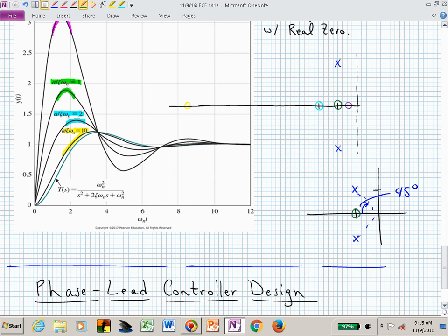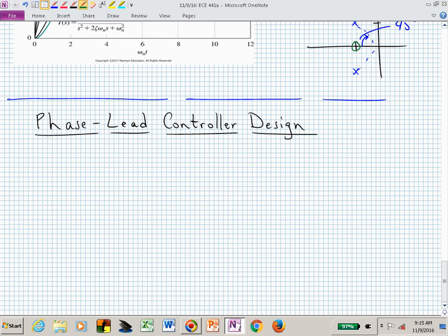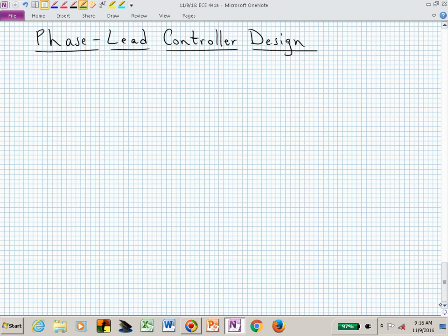So you have something that looks like the pure two-pole plus the derivative of that, combined because of that s in the numerator. And that combination of two pieces gives you this additional overshoot that you wouldn't have had if it was just a pure two-pole system.